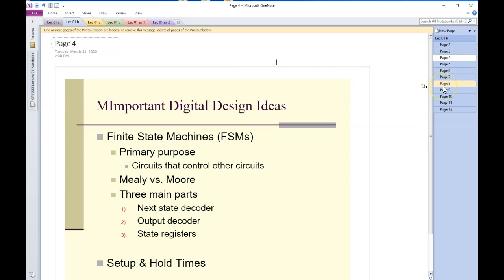This was a super important concept. We kind of brushed over it in 133 simply because it's something that's hard to test. The issue here is you can just speed up your clock cycle, and at some point your circuit's going to fail, and it's primarily going to fail because it missed a setup or hold time.